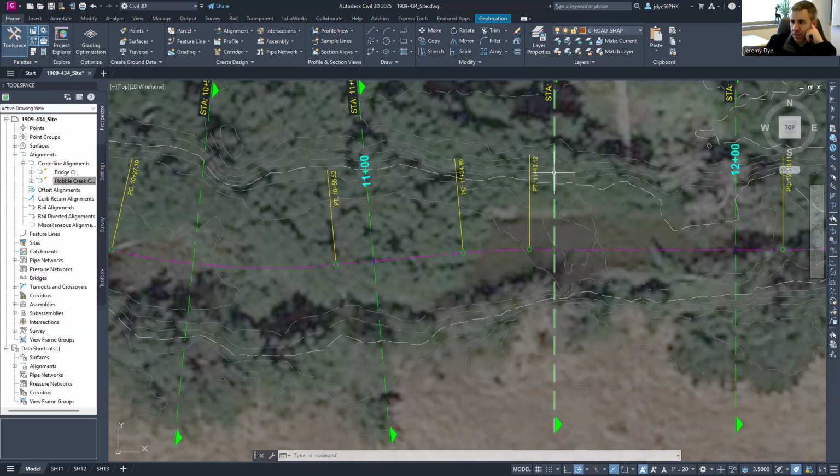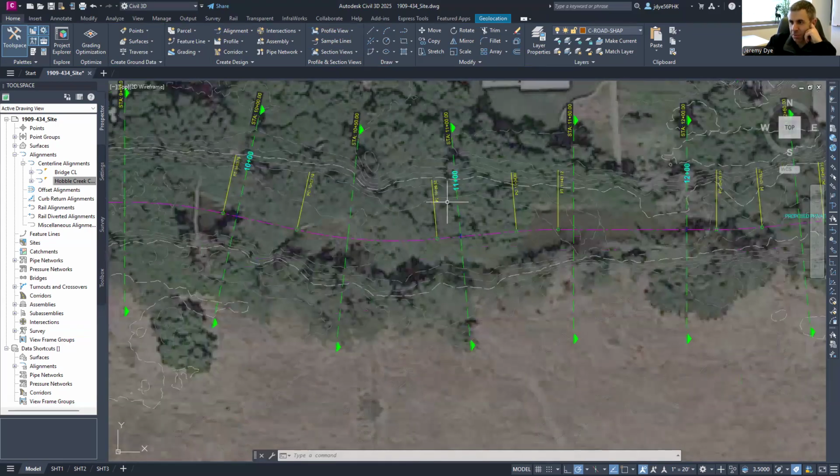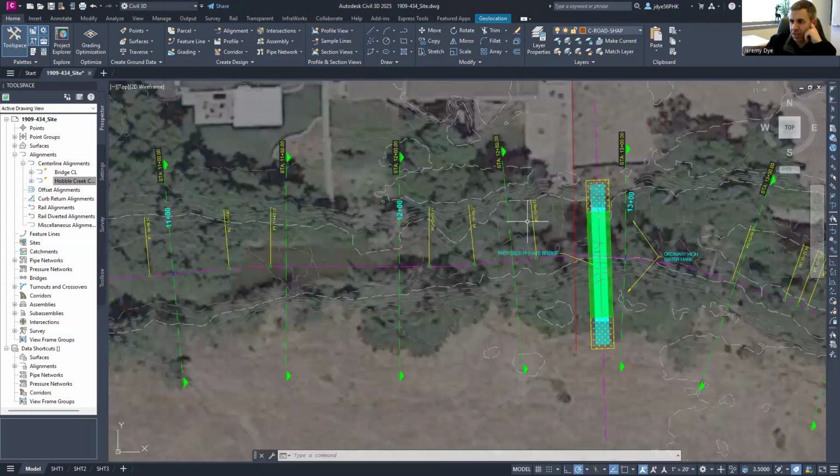And the more friction there is, the slower the water is going to go. So the water here in the middle, where it's used to flowing, is going to have fewer obstructions, less friction, and the water on the banks, where there's trees and rocks and things like that, will have more friction. So we're just trying to identify the place where that friction or that Manning's n value changes.